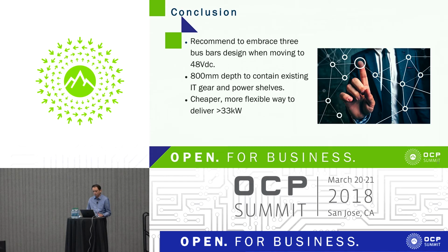For the existing IT gear and the power shelves, the server and storage solutions we are selling are becoming deeper and deeper. So 800 millimeter can actually provide better thermal between the device and the bus bar. It is also a much cheaper and more flexible way to deliver more than 33 kilowatts or even further.